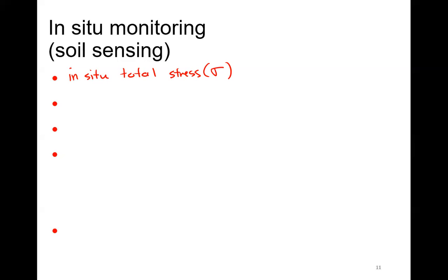Estimated gamma values and the heights and the geometry and all that stuff. But we can actually install equipment that can measure this. The thing that's most common is what's called a pressure plate. These all have fun names too, just because contractors work on them. So these are sometimes called pancake plates, and you'll see why in a picture here.